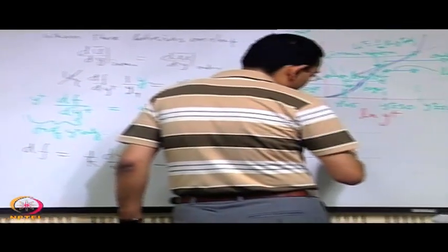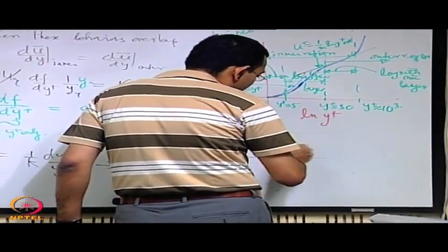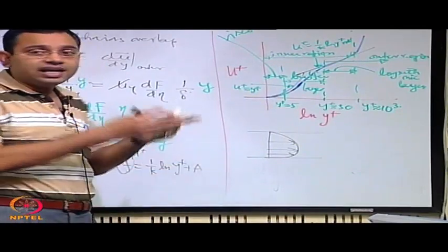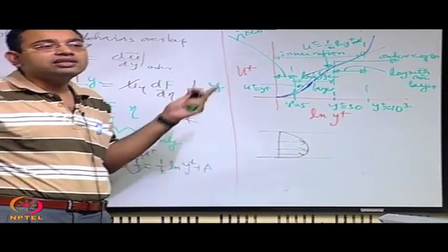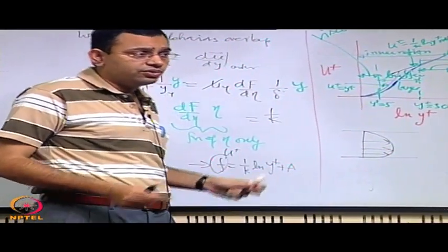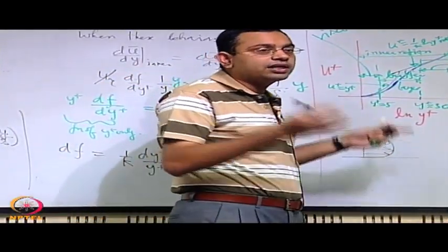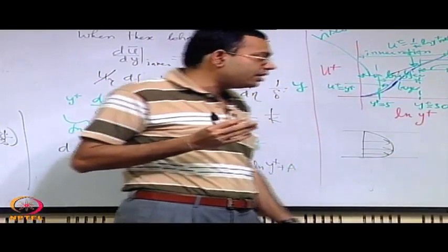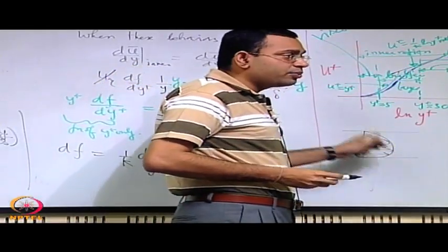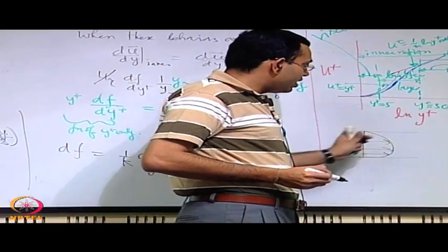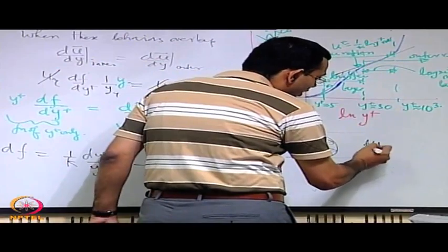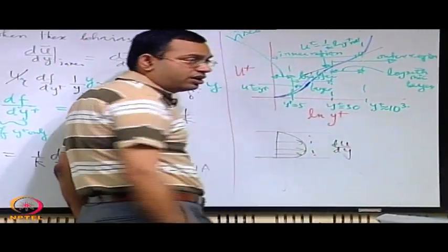Say you have a parabolic velocity profile in a channel flow, and this velocity profile is there in a medium where the viscosity is 0, or say it is an inviscid flow. Then if there is any perturbation, the perturbation will dampen out. There is a fundamental theorem which says why it will dampen out: this velocity profile does not have a maxima in the vorticity, that is, a maxima in du/dy, anywhere within the domain other than at the wall.